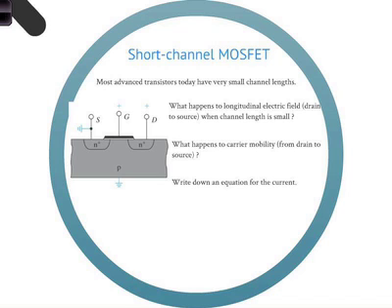Of course, the charge Qn, the first term there, depends on the gate voltage, clearly, which is more complicated, but it's the same as what we did before. So you've already seen that before. So approximately, more or less, that's it. Oh, this is an even simpler way to think about it. You can think about it from a capacitance perspective. So the Qn, so this part here, let me just rewrite that.